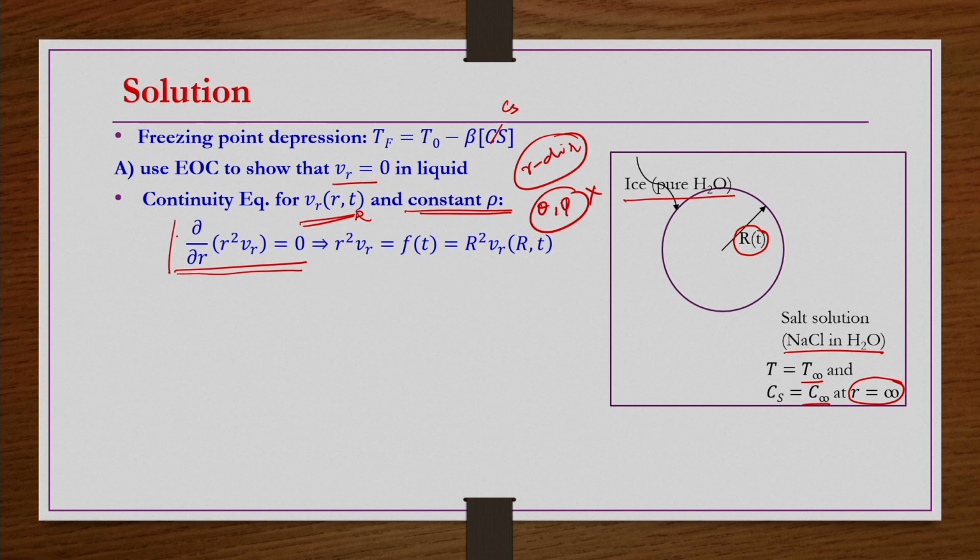So, in the continuity equation I am writing only the term which has r coordinates, the function of r. V theta and V phi terms I am not writing because it is clearly mentioned, and we have already solved so many problems, we know how to do that. So, we get dou by dou r of r square Vr equals 0, that means r square Vr equals a constant, but that constant is a function of time. It is independent of r, independent of space, but dependent on time.